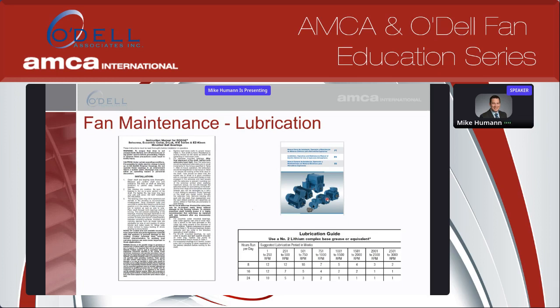Following the fan manufacturer's and the motor manufacturer's guidelines is certainly going to help your fan be serviceable for as long as possible. We see fans go all the way to 40, 50 years. Design life is typically centered around 20 years. Obviously there are different applications, but certainly lubrication is a really big part of fan longevity and fan maintenance.